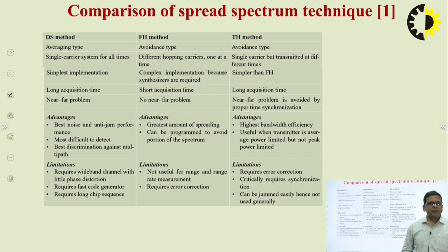Direct sequence spread spectrum suffers from the near-far problem, but frequency hop and time hop spread spectrum avoid the near-far problem. So, these are the different comparisons on which we can select the spread spectrum technique according to our applications.